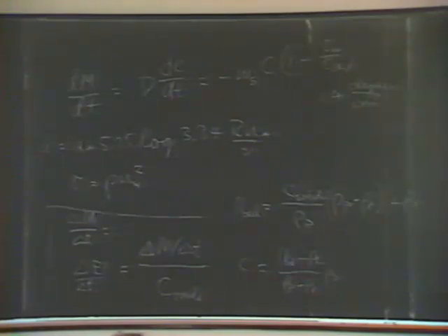Well, they didn't take into account the fact that waves stirred that sand continuously, and when they lowered the depth of the channels, the sand would funnel into it and reestablish the existing slopes. So at first there'd be a lot of sand coming in, and that would quit after a while, after the new slopes were reestablished.